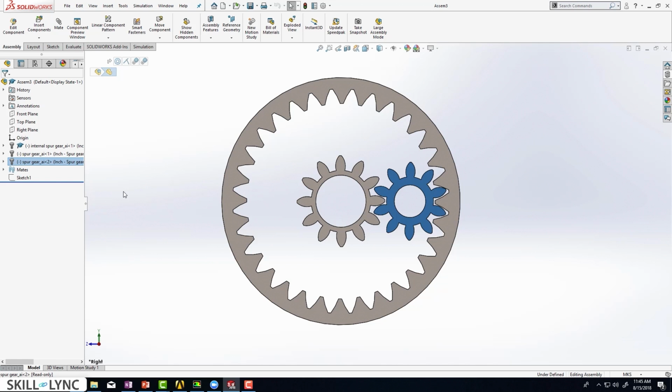Now we can start by creating our own gears in SolidWorks by sketching and then using an extrusion operation. That is unnecessary because SolidWorks provides a library of gears according to different standards, and we can use this for our purpose, and that's exactly what we are going to be showing you in this video. In this case we need a sun gear, a planetary gear, and also a ring gear, and we can just use the design library to import the appropriate models. Now remember, the internal gear is an internal spur gear, whereas the other gears, the sun and the planetary gears, are just spur gears, right?